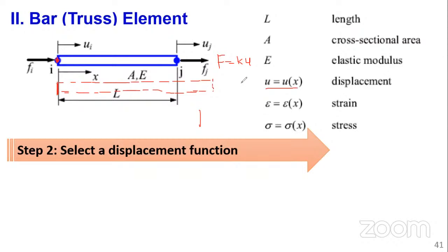And that's why our assumptions are very important. Geometrically straight, material obeys Hooke's law. Okay? Because if the material obeys Hooke's law but the geometry was varying, then maybe the deformation at different points, or the elongation, would not be linear. But let's not get there too fast.